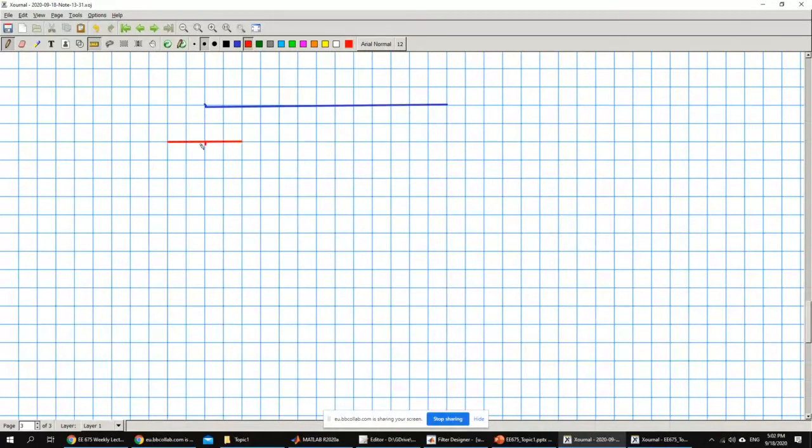This is the center point of the filter, and just say that this is 0, this is -1, this is -2, this is +1, this is +2. Okay, and this is a signal here. You're going to have the same exact signal. This is signal number 1, 2, 1, 2, 3, 4, and so on. Okay. As we said last time, you take the filter, flip it, and keep shifting until you get inside, and each time you multiply, add, and compute the point.